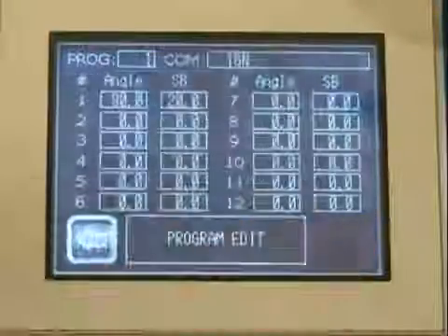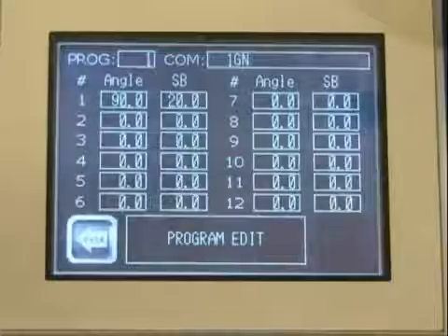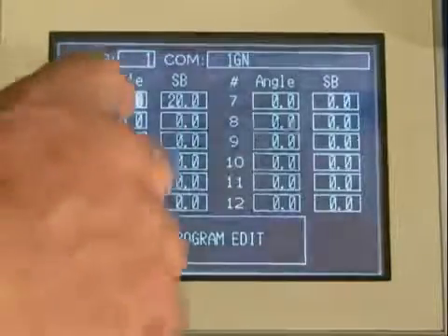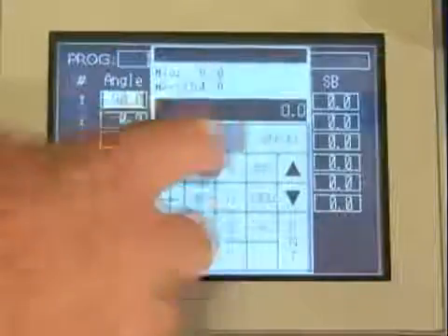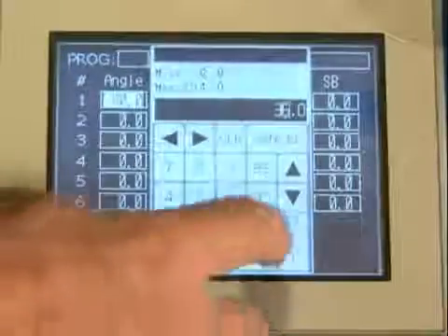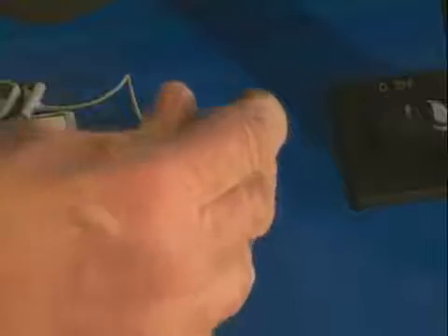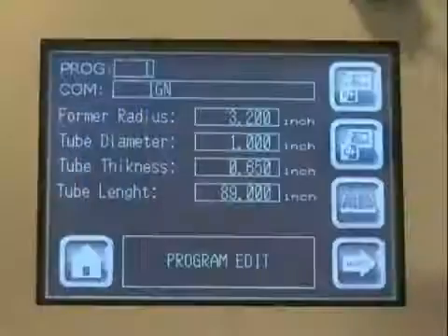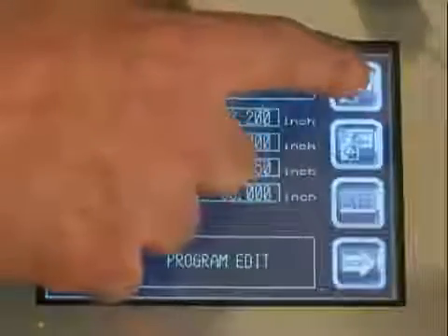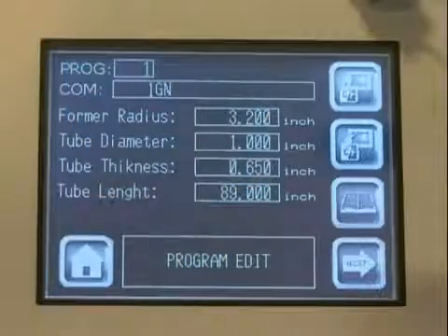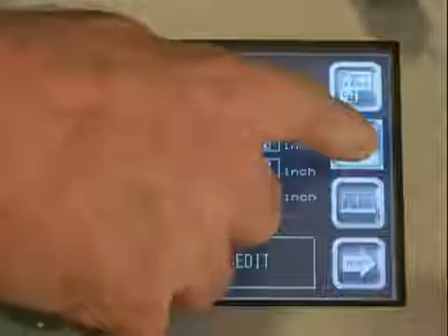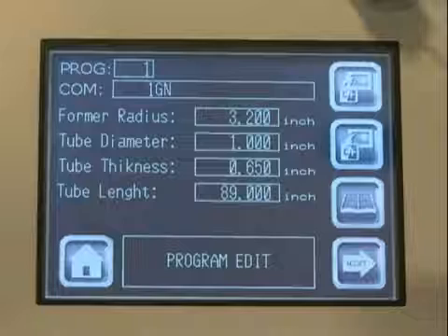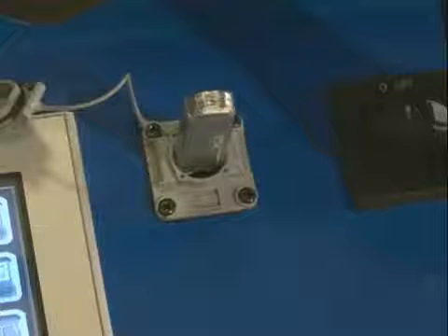Should springback and bend angle values require editing during the bend cycle, simply stop the bend, go to Programming, and make the desired changes. After creating a bend program, the operator can load an existing program from the USB to the control or transfer the current program on the control to the USB by simply selecting the appropriate icon from the automatic screen. The information is securely stored.